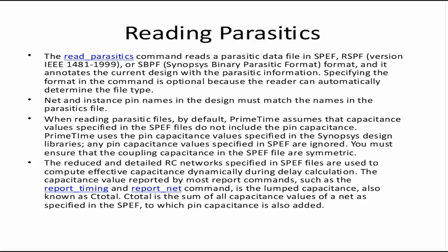We have to note that the value of capacitance we see in any of the commands is the lumped capacitance or C total. C total is the sum of all capacitance values of a net. Usually in most cases it is the sum.